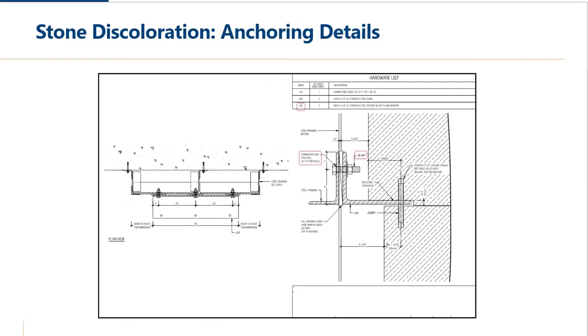Stone anchoring details indicated various anchorage types and dimensions for lateral attachment of the marble units, typically including discs, dowels, and bent plates that engaged curved slots cut into the stone. The elements in direct contact with the stone were type 304 stainless steel. The drawings show the curves and holes at stone attachment locations to be filled with sealant.